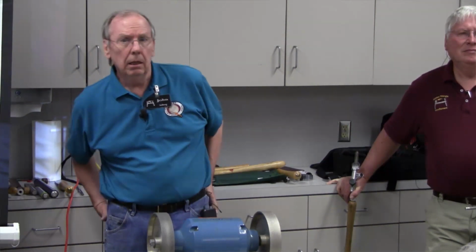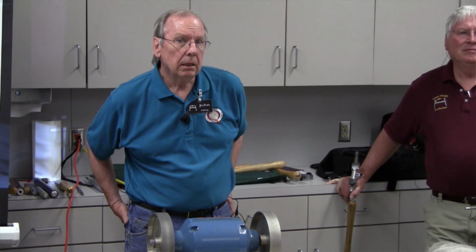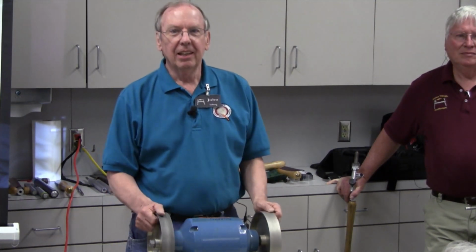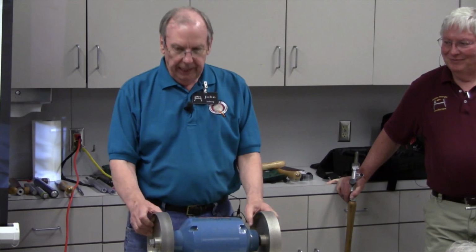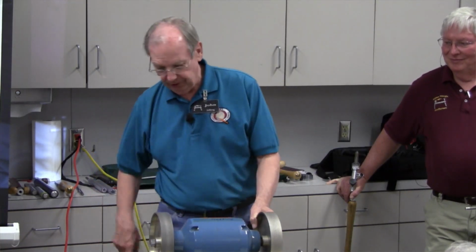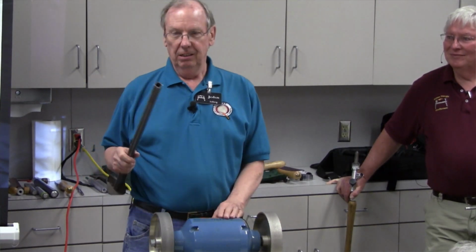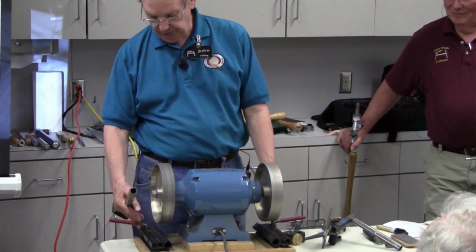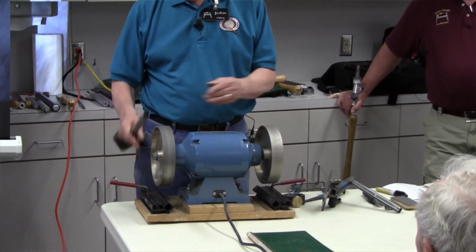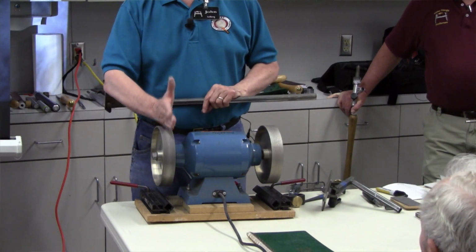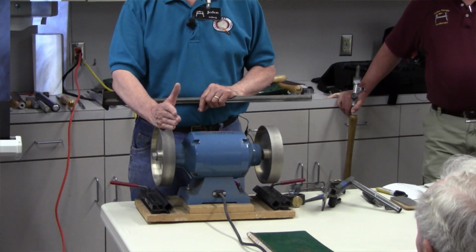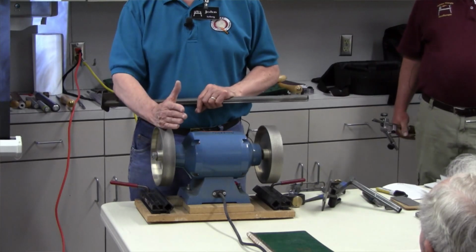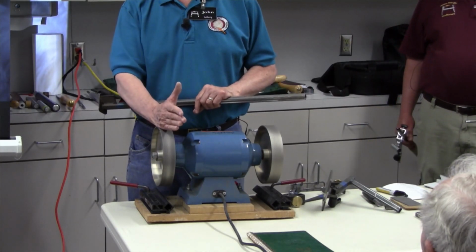John, would you discuss the importance of setting up your guide rails and so forth, and the issue if you get a pop one way or the other? When you buy a grinder and you buy the Oneway system, it's absolutely critical, and Oneway sends instructions on how to do it, that the system be set up absolutely perpendicular to your wheels and centered on the wheel. We spent some time this week with a grinder that was not centered and not straight, and you do not get good grinds when you do it.